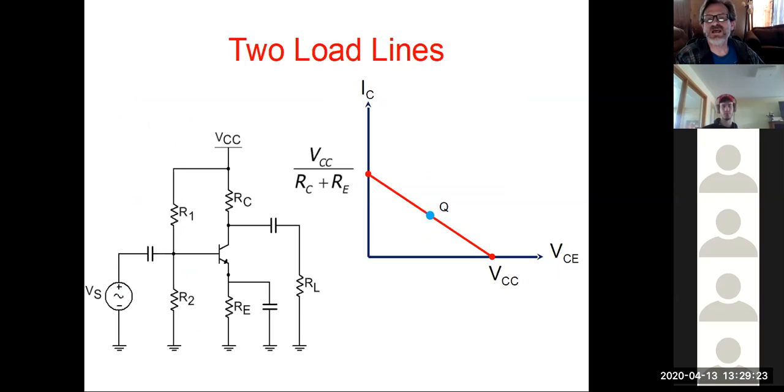And here's a good example. The first part that we're looking at, you notice we're using all capital letters, so this tells me that we are doing DC. Our DC response overall, notice we're using IC compared to VCE, goes from saturation to cutoff, so our ideal point would be in the middle, okay? We look at the DC bias for the circuit, ignoring the AC for this point, and go ahead and draw our load line. This is our ideal response. Maximum IC is the saturation, and of course, maximum VCE would be cutoff. Ideally, we're going for that middle range. All right, click the next slide.